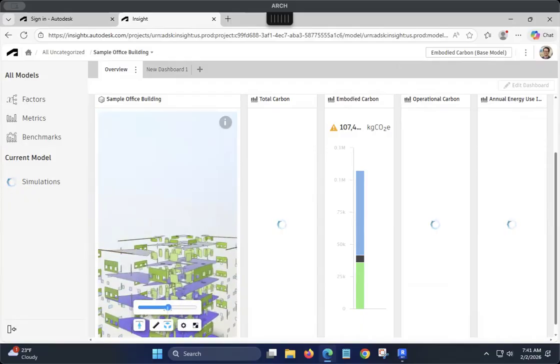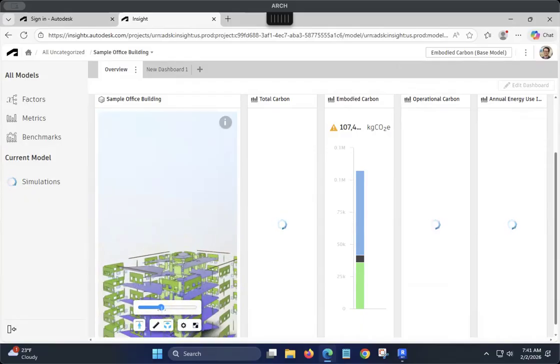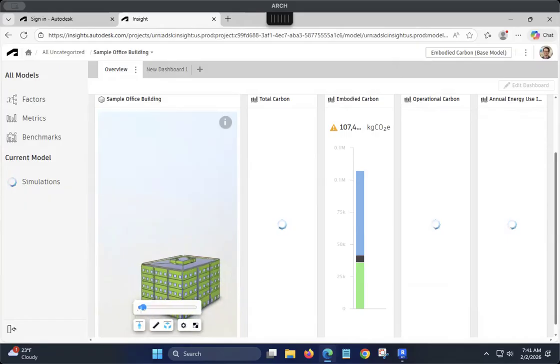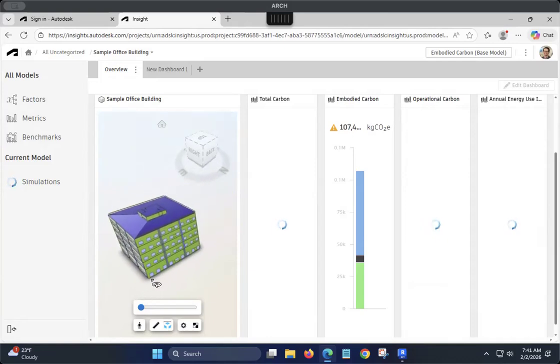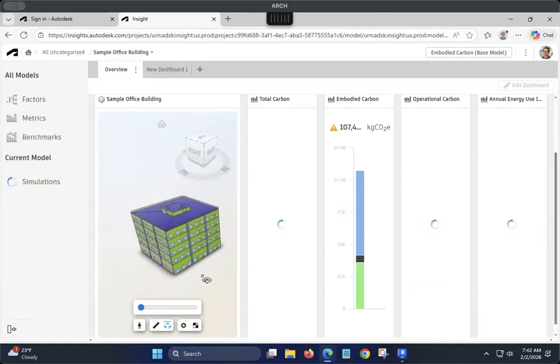If you're unsure what's inside the model, how it imported it, if the interior walls, for instance, were conceptualized properly and brought into the model the right way, you can find that. And it's important to do that because there are times when Insight will actually not interpret your model completely the right way. That might be because of something that was not accurate in the modeling itself. Maybe you or your team didn't define some aspect of the model accurately. And so it is good to do a quick quality assurance test on that geometry.